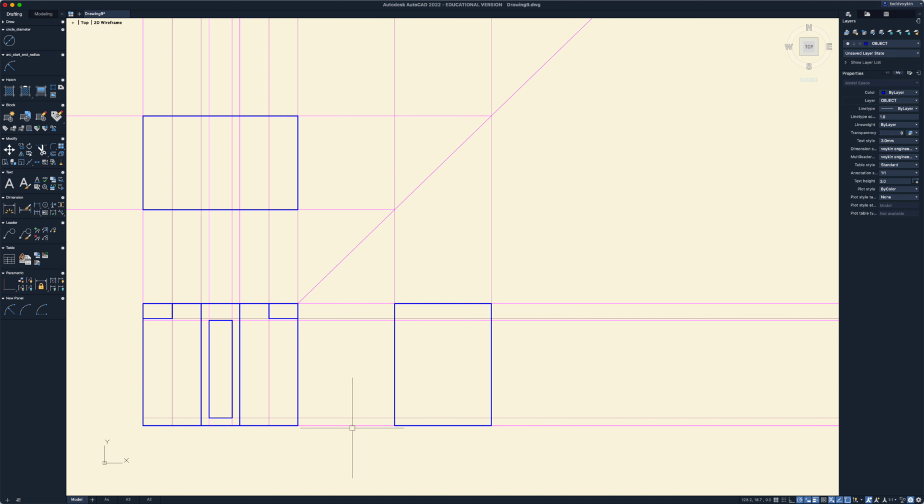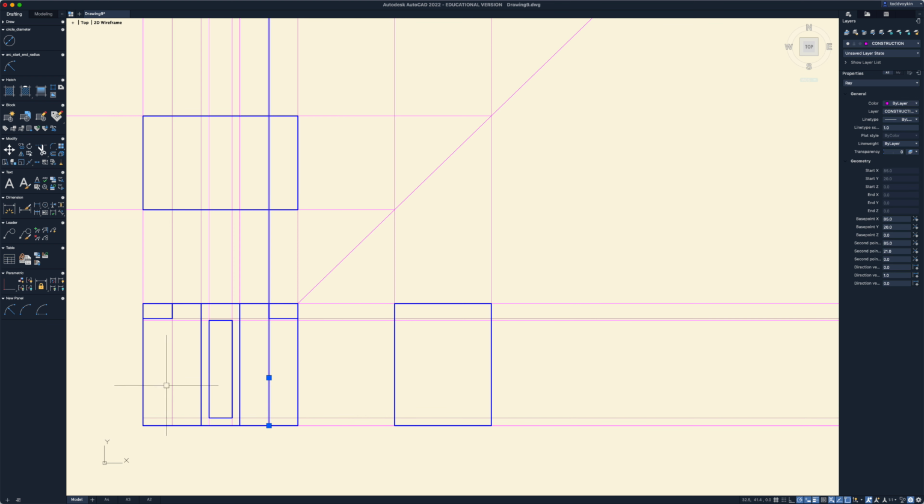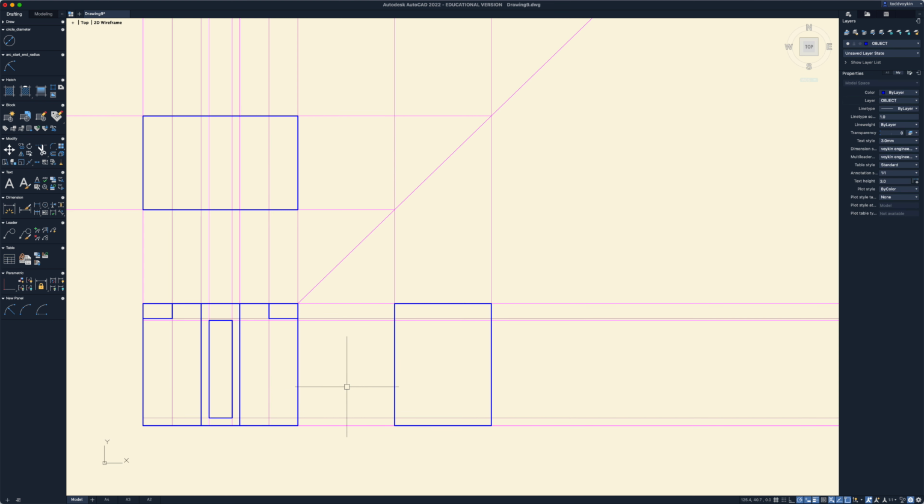So we can go back into creating a few more of our construction lines, and I'll create the center points for the circles. So I've already got this line right here and here, which is our center point right there, but I need the dimensions going up. So offset 10 to begin with. That one's going to go up 10, and then that one's going to go up 15, and that one will go up 15, creating 1, 2, 3, 4, 5, 6 center points.